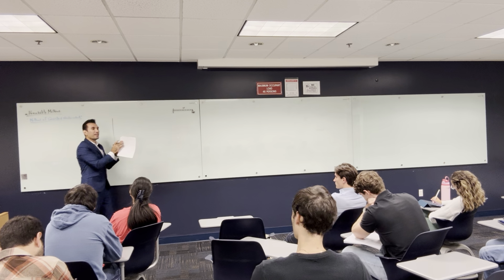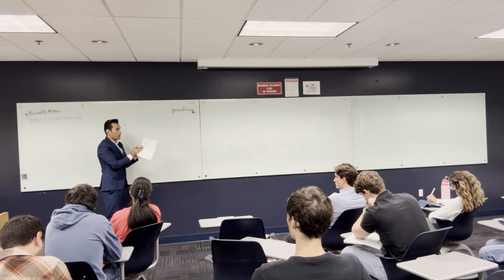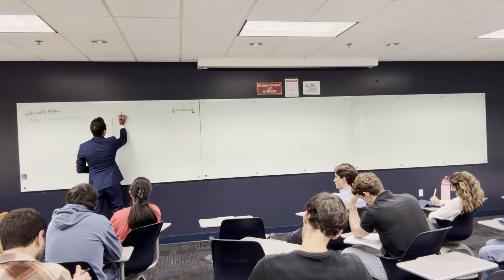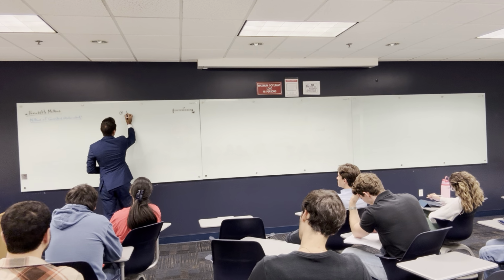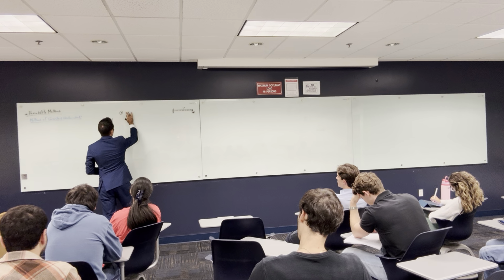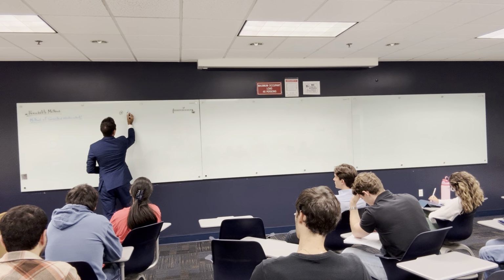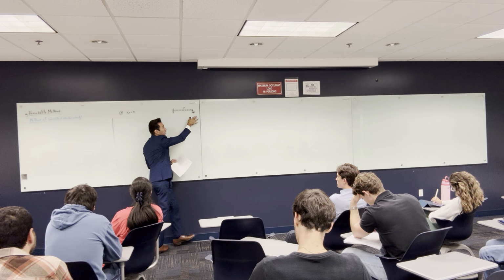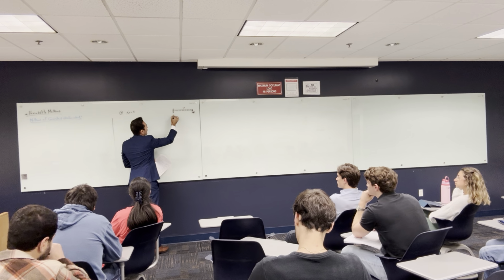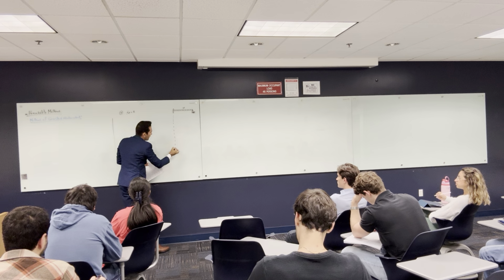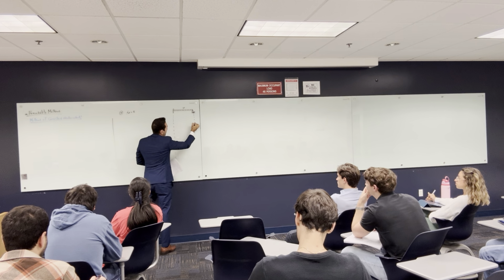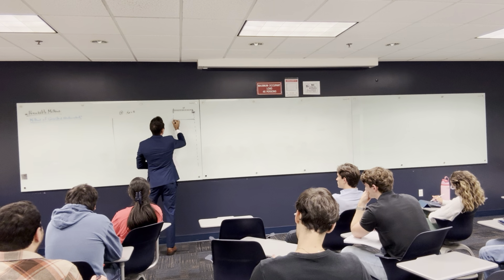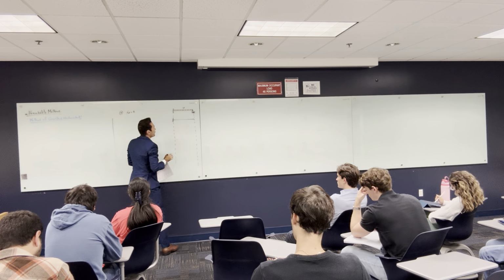I put the steps here for you in the notes. First one, determine the degree of indeterminacy. So can you guys tell me what the degree of indeterminacy is? 1, right? So IS is equal to 1. So basically I can remove this roller or I can make this a hinge, right? I'm gonna remove the roller, and this is gonna be my structure.